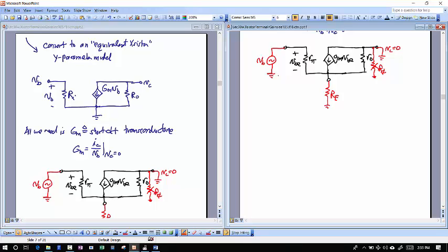So the first thing I'm going to do is what we usually do. I'm going to neglect R naught because it's very large, I'm assuming, versus all the resistors that I have in this circuit. And then I'm just going to start my analysis. So the first thing that I can do, for example, can define a voltage across RE, call that VE, and I can write that voltage here. That's going to be all the currents going into RE times RE.